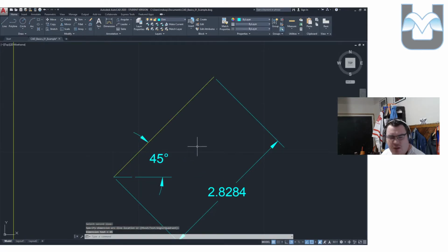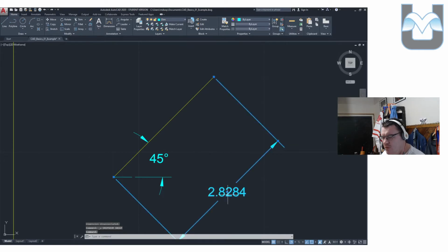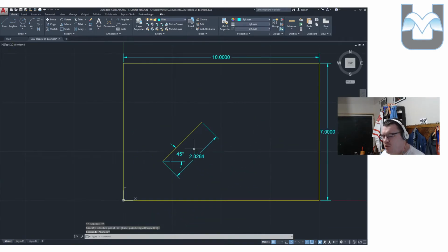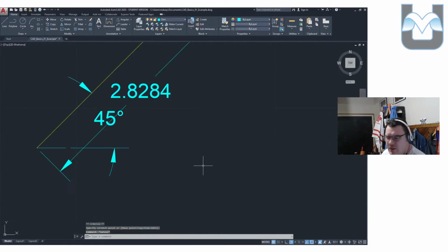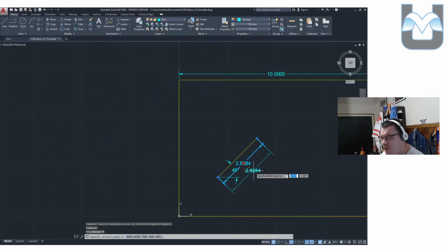In this case, that angular dimension is 45. I think it's 30 if you're doing the assignment properly. I'm just going to move my dimension back in place. One thing I really like to do is grab the whole dimension, not just the number. I like it so that in my drawings, the dimensions don't cross as best we can. This is something you're going to try to do to make it very clear what's what, because as soon as things start looking like this, it generally becomes a mess. So be clean with your dimensions.